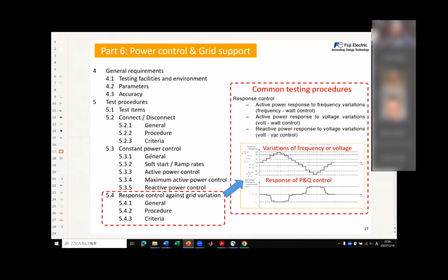And also here you have the constant power control. So you can change the feeding active power or add reactive power as you want from the PCE. But we have to consider the input current from the DC side. Like PV inverters, we cannot manage the level of the input current, and at that time, we need a storage. At that time, we can control the active power. In terms of reactive power control, like a STATCOM, PV inverters can control it as they want.